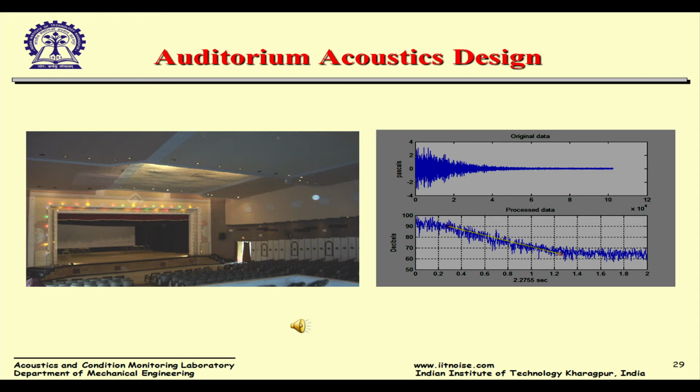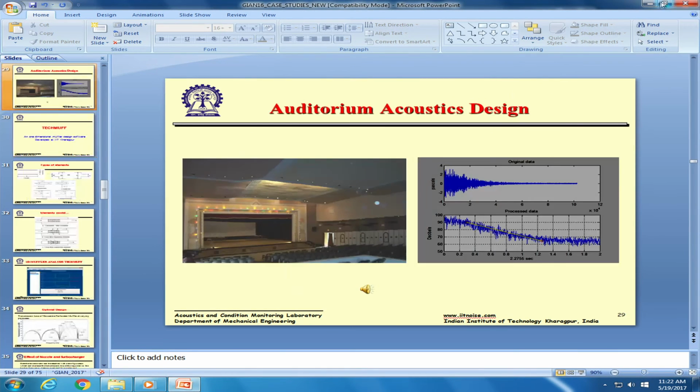Yeah, we talked about auditorium acoustics. Another few things which we do is having the right acoustical material to control the reverberation time, where to put, how much to put, and I will just play, if I can play this, how this impulse looks like, or how it sounds rather.